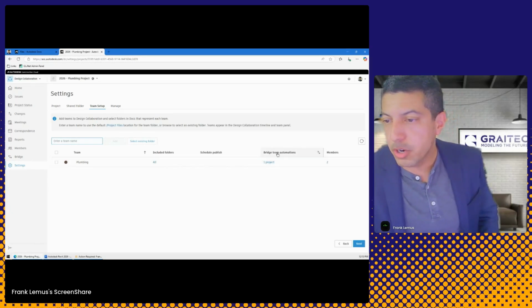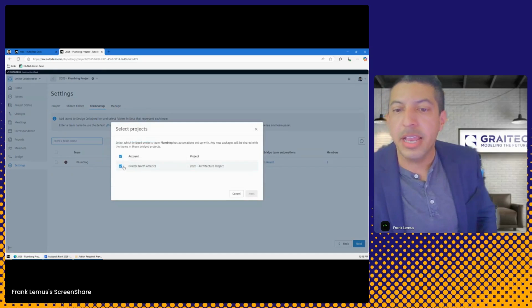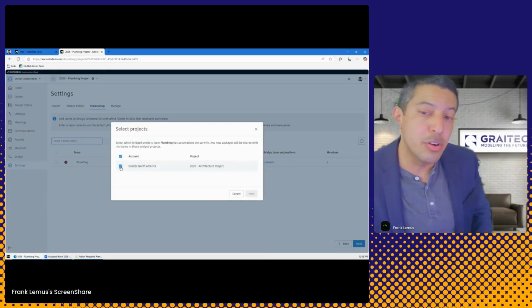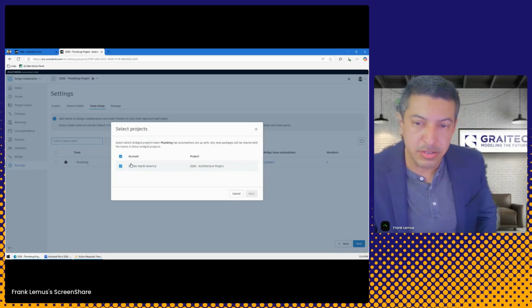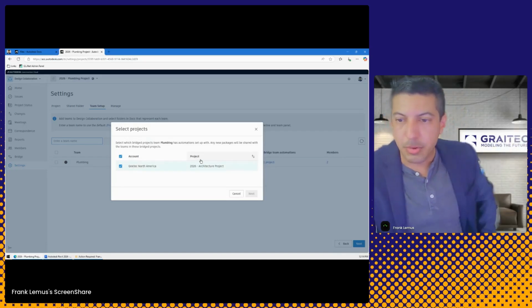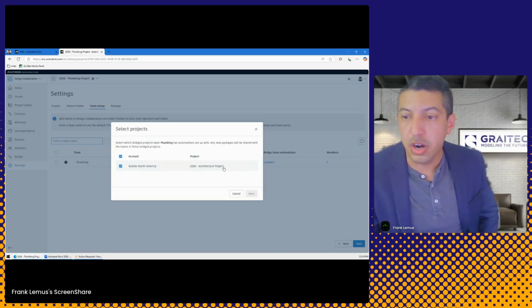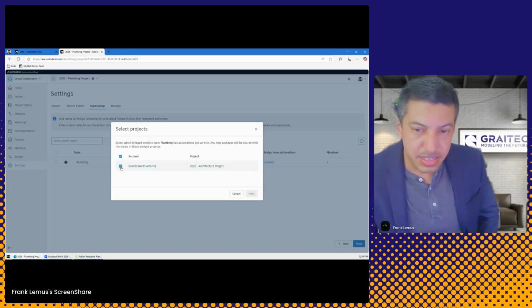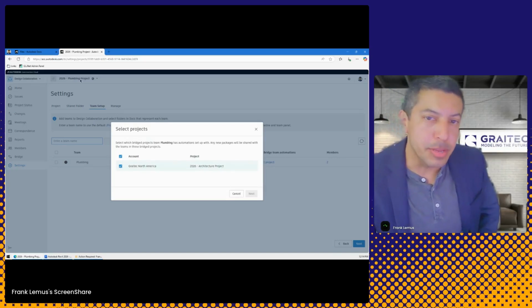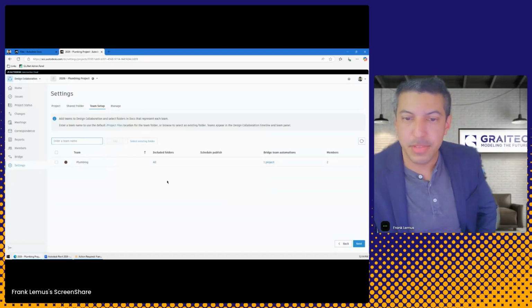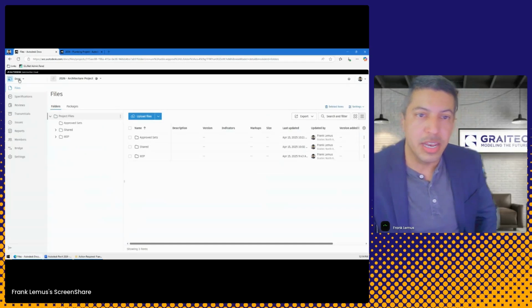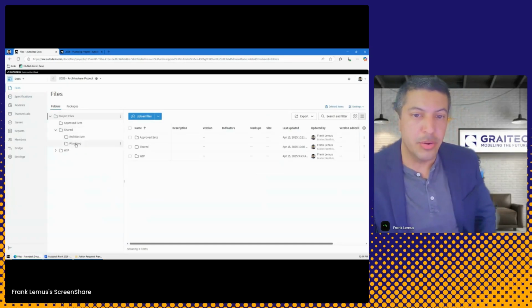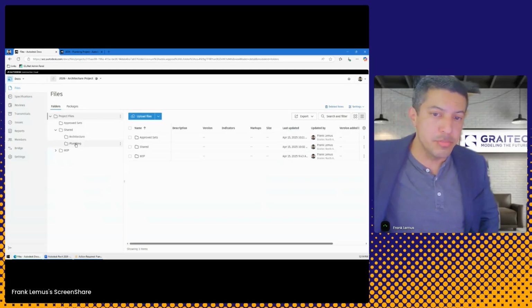So plumbing, I'm going to go to bridge team automations, and here's where I would have selected Graitec North America as the account, that's the architecture side, and the project that this is connecting to is the architecture project. Because I clicked on this checkbox within the plumbing, and I didn't do anything else with docs, when I go to the architecture side, I don't even have to go anywhere else. Even from within the docs, I can see that my shared folder now has the plumbing's packaged folder.